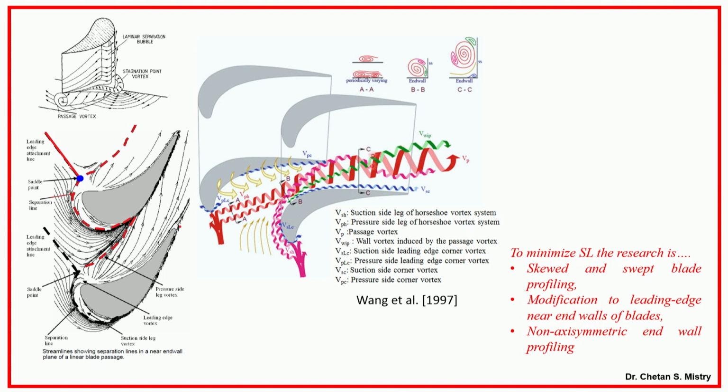So all together, they combine to form one big vortex. That vortex we define as the secondary flow. So the thing is, we have boundary layer growth along with my pressure gradient near the end wall, and that is creating this kind of flow structure.